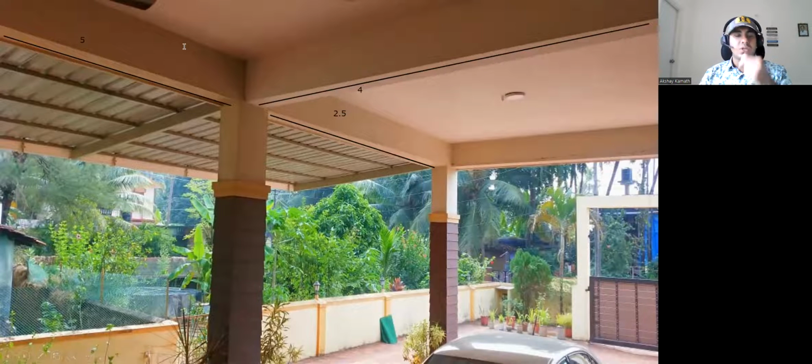Now you tell me from which side your depth of the beam will be. This is 4 meter. I don't have a beam. Forget about this. This is not a beam. This is the additional thing we did later. Imagine there is no beam in this direction. So this column is getting pulled by 4 meter in this direction, whereas this column is getting pulled by 5 meter in this direction and 2.5. That means the net is 2.5. So out of 2.5 and 4, which is more? 4 meter. That means the depth of the column should have been in this way. The column should have been like this, right? Actually, according to our logic.